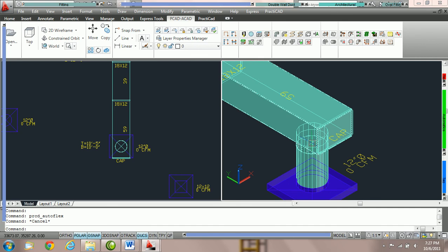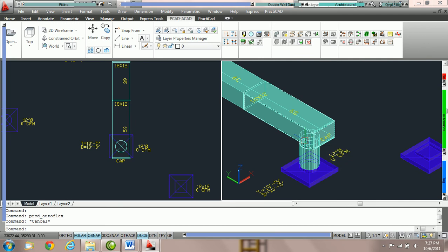But the fitting right here where the cursor is, it's not highlighted, it's behind the fitting in the isometric, is the spin collar accessory directly from our catalog. So this is an example of why we'd want to use the spin collar accessory. It's talking about tapping to the bottom of duct that we are using to route to a grill.